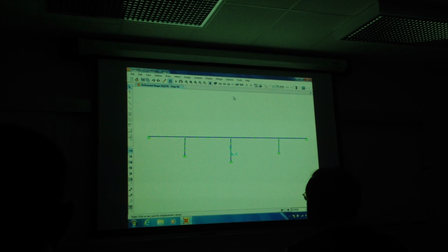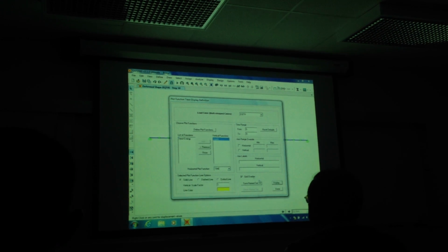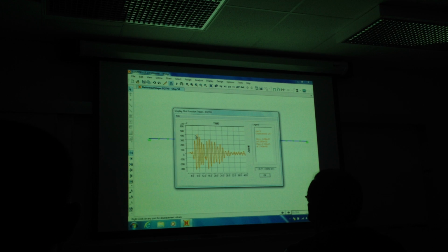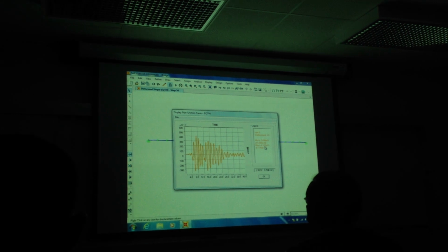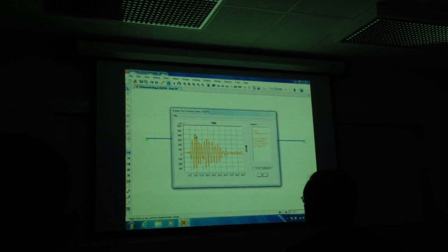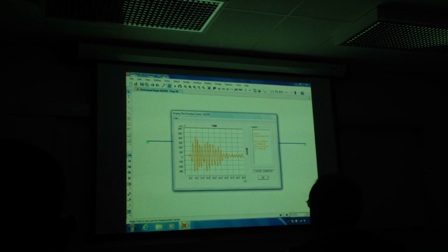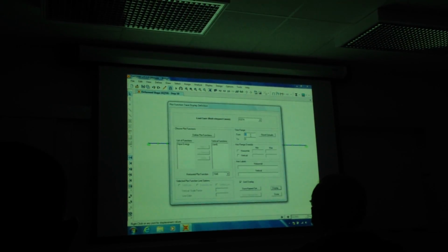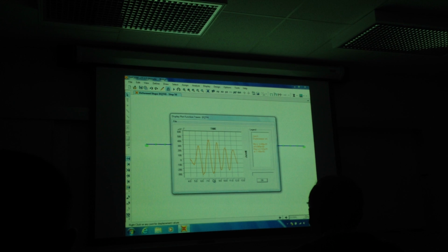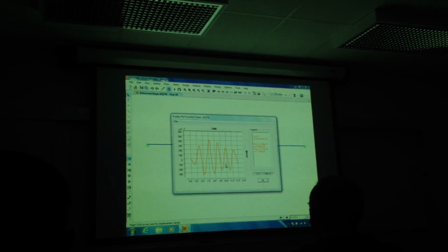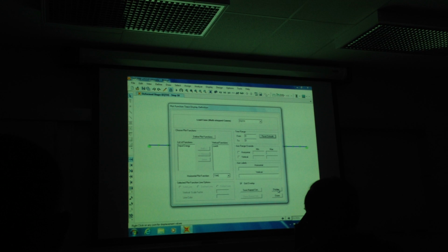Yeah, we're going to try creating a video too. Let's do this first. So joint 6. 0.4, just over 0.4 feet, so that's about 5 inches of displacement. That's it, you can see it right here. If you want, you can zoom in, display it again. Let's say between 4 and 12 seconds, okay? And you can always save this as a file into Excel or some other program. See, so you can see what the vibration characteristics look like. Then you just go back here to reset default.